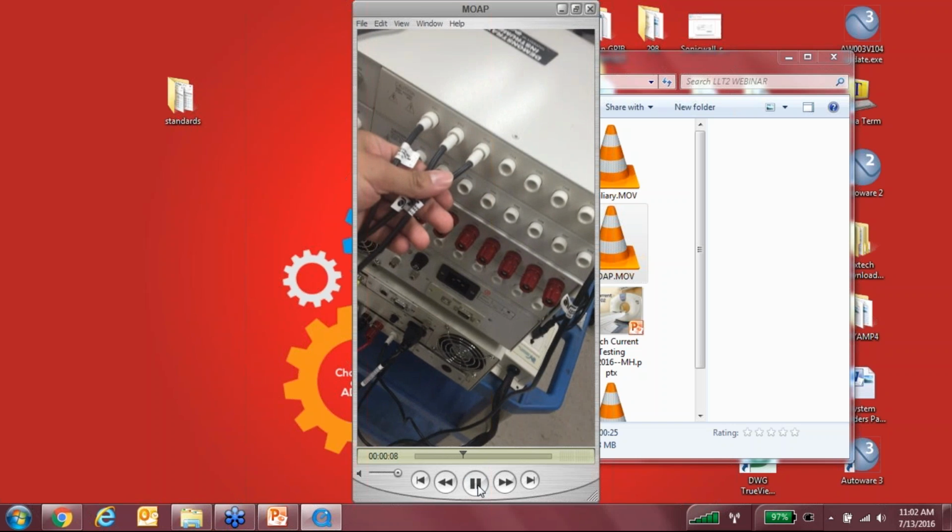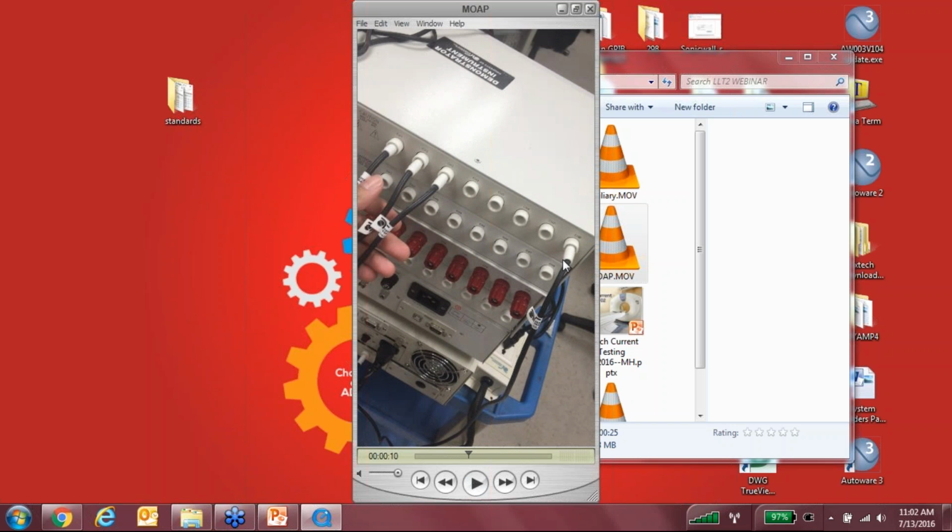And if you look on the far right side of that scanner, I have my probe low. So now I can short two of these. I can short my line with my probe low, have my neutral and ground shorted, or reverse polarity, my neutral and my probe low, and line and ground shorted. So that's how you achieve that.